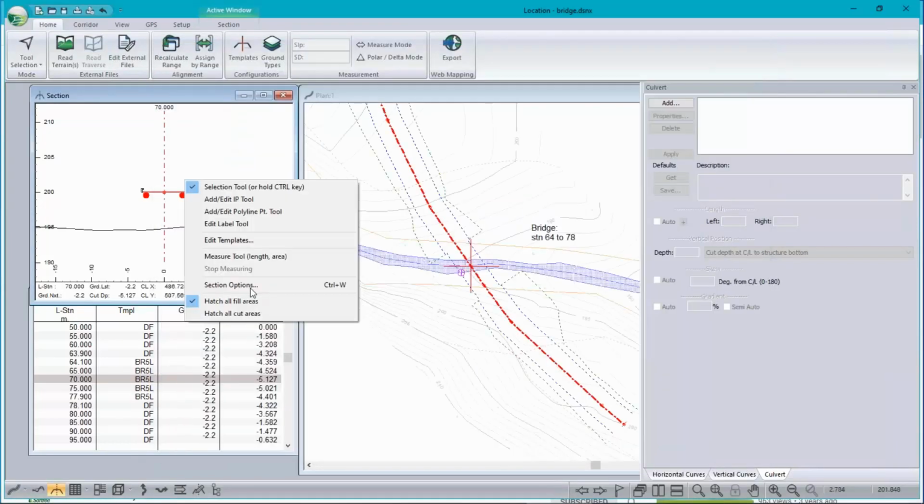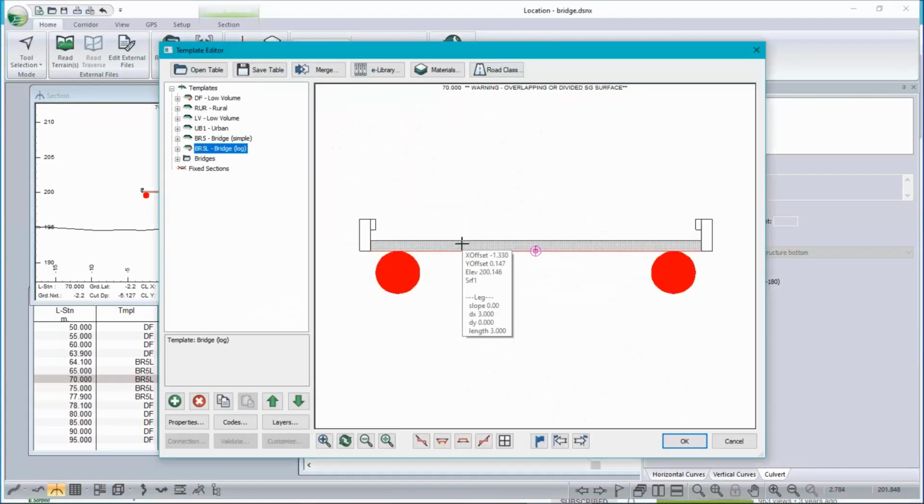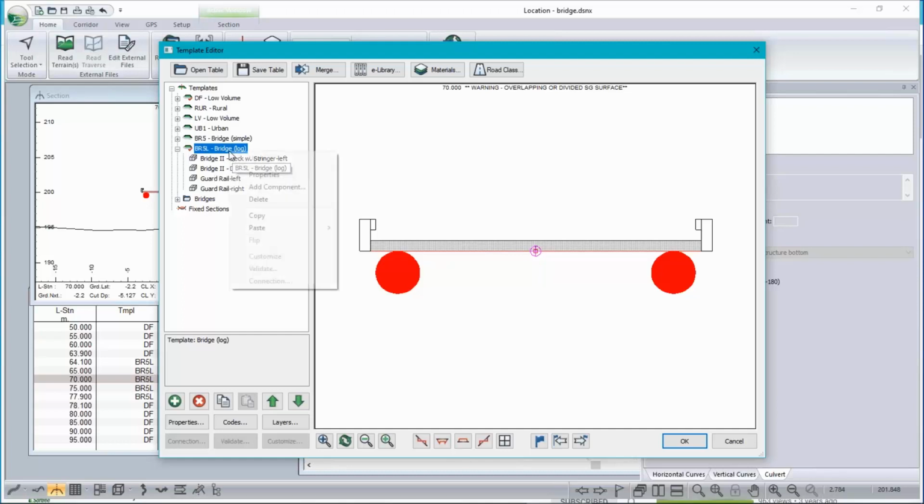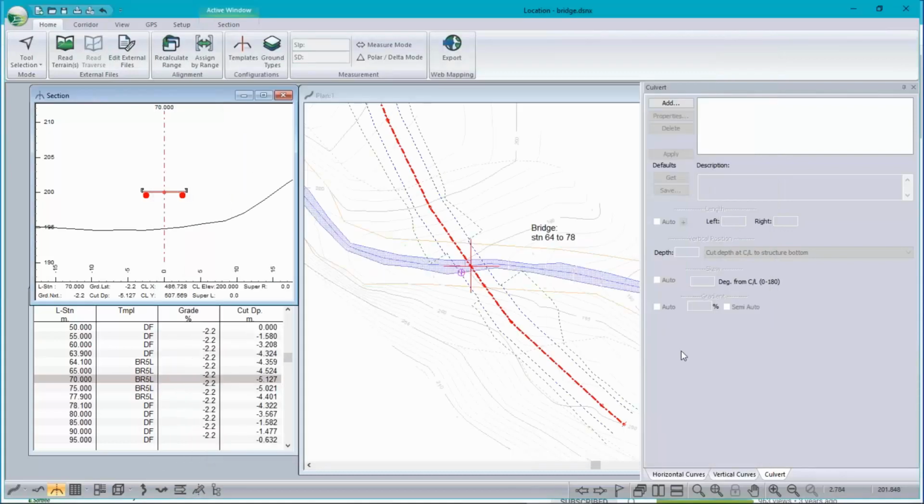Okay, and the important thing about that bridge is that it doesn't create volume underneath, so I don't have to worry about counting volumes incorrectly. You can turn the volume for the whole thing off if you want, right here. There. That would turn off volumes for the log and this cross-section and so on. Okay, so if you are getting volumes you don't want, there's the place to turn it off. I'm going to skip out of here and go back to where we were.